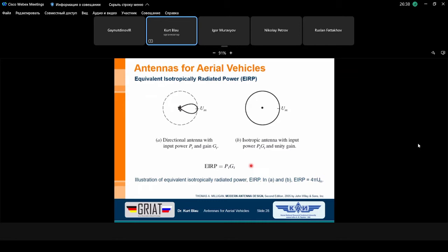No, this is the power which is allowed to radiate in the free space. If the antenna has, for instance, a gain of 10, then the applicable power is only 10 milliwatt, because the antenna gains this power again by the factor of 10, and so it radiates in a certain direction in the free space 100 milliwatt.